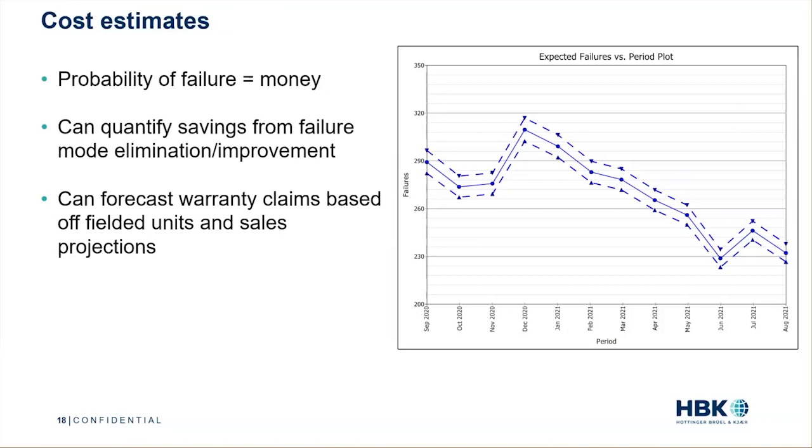Furthermore, you could say, well, if we could get rid of this mechanical failure mode at the module level, we would increase our reliability by 2%. And 2% corresponds to this much money, X dollars over however many thousand units. So that probabilistic model really helps us communicate this beyond us engineers. We understand the benefits of this type of reliability analysis, but this really helps us communicate it to non-engineers, to our managers or people making decisions, to justify test activities, analysis activities, R&D activities.